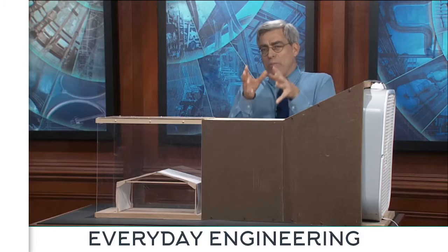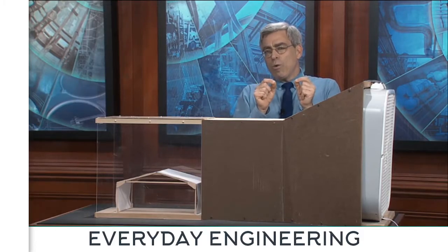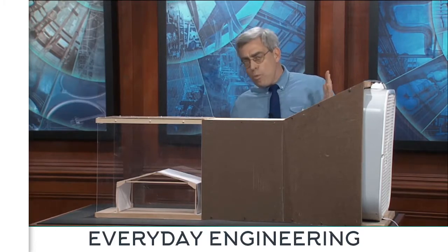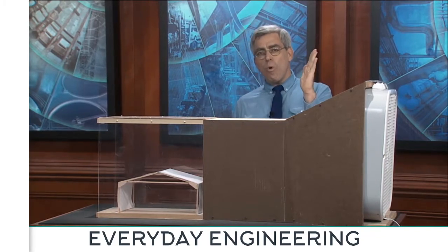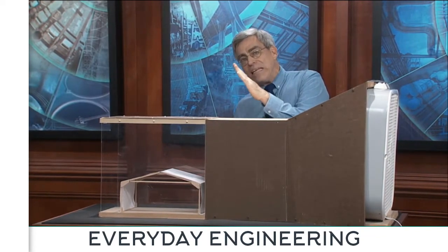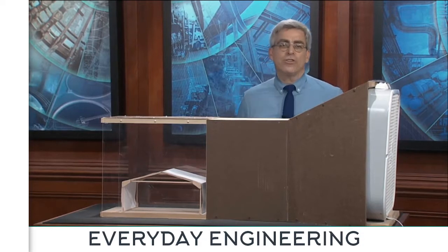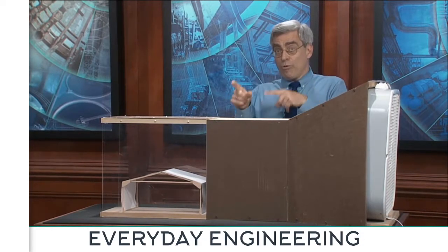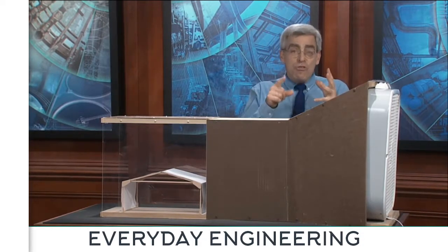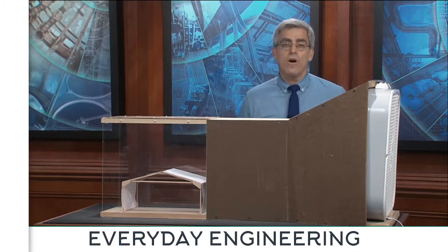Well, as you've probably predicted, the moving air will exert pressure on the upwind wall of the building, pushing the wall inward and causing the building to lean a bit in the downwind direction. In hurricane-prone regions, this pressure could be upwards of 40 pounds per square foot.